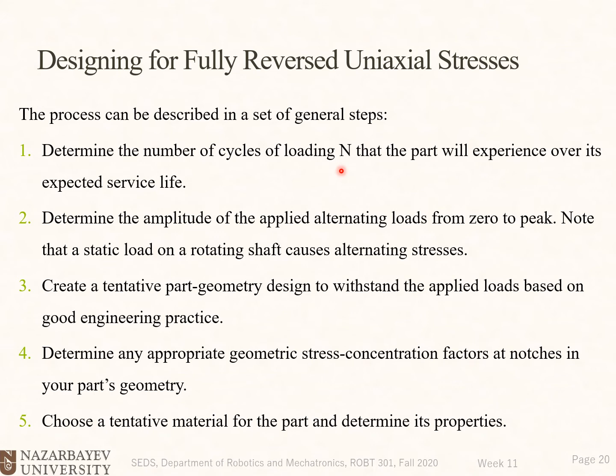Or at least, how many cycles do we expect that shaft to withstand the load without any failure? That number of cycles will be N. This is something that we should assume or should be given for our design based on our service life.